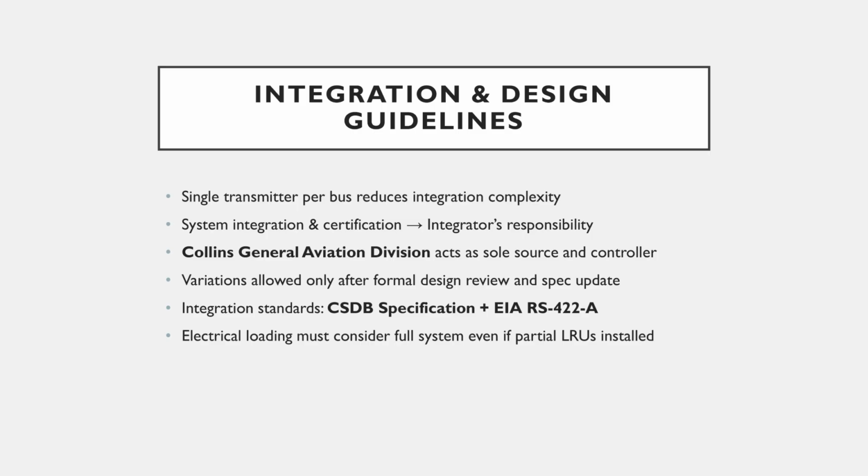With only one transmitter allowed, CSDB simplifies integration, but it does not define system-level architecture. Collins controls the specification, and deviations require formal approval. Designers must consider full electrical loading even if the installed system initially uses fewer LRUs.